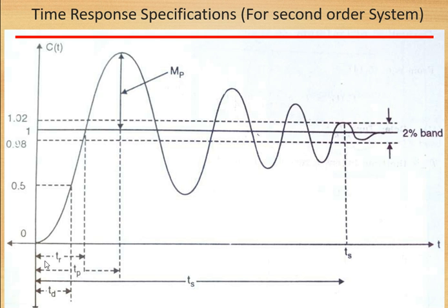Okay, so whenever the system gives you output after giving the input, it will not be stable at the desired output, it will go above that, and that is called overshoot. After that it will give you undershoot, again overshoot, undershoot, and as it is a damped system, though it is underdamped, it is damped, that's why this amplitude will become smaller and smaller.